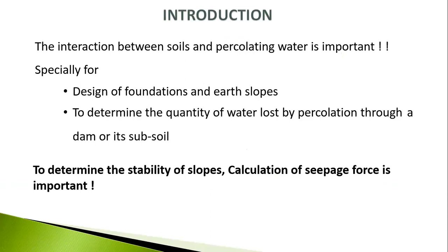When we design any foundations or need to settle any earth slopes, we need to know the seepage conditions of that circumstance. Another aim is to determine the quantity of water lost by percolation through a dam or its subsoil.